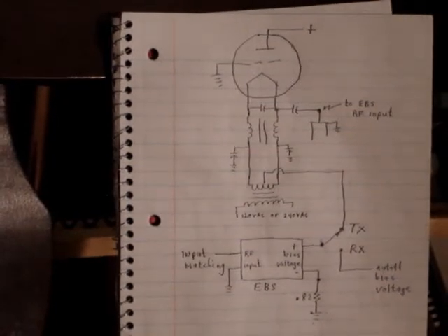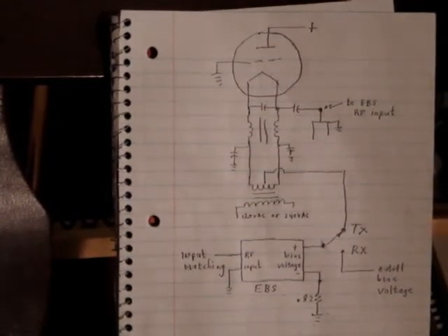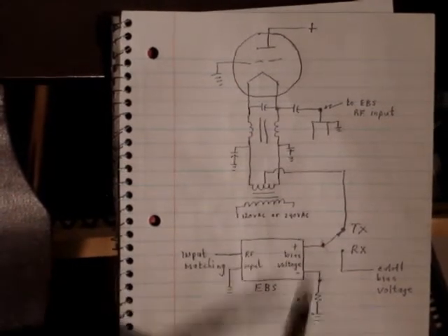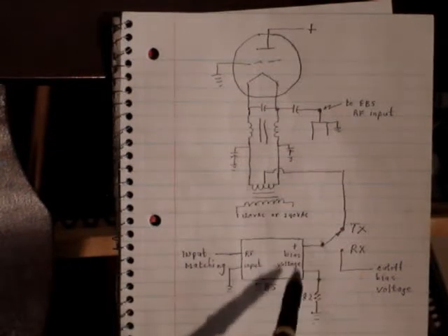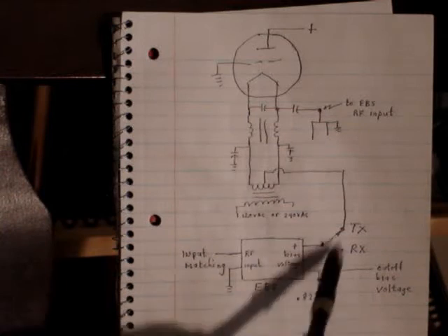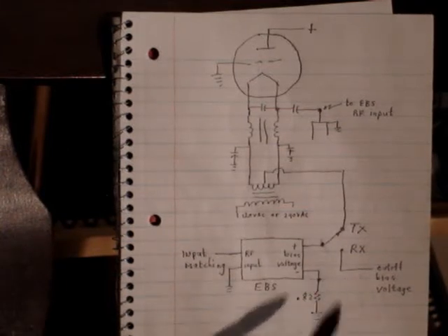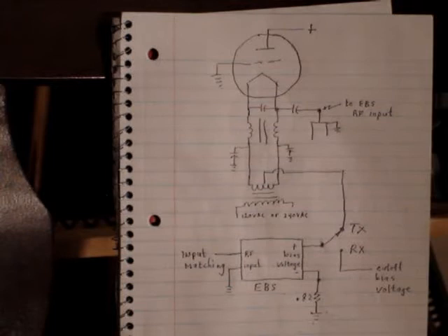So the nice part about the electronic bias system is it really doesn't require a major change to your amplifier. And really, to go back to the original design, you can just take off the voltages, or take off the wires that were attached here, enable the Zener diode. What I do is I just put a short wire across this, or remove the short across the Zener and connect these wires together again with the Zener down here, of course. So there we go. Now let's see what this can do for you. We'll start working towards what this looks like in a real amplifier now.